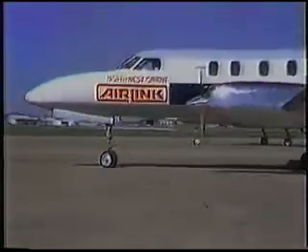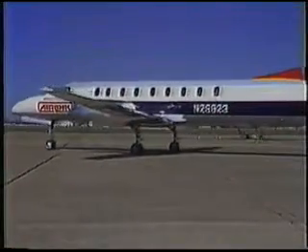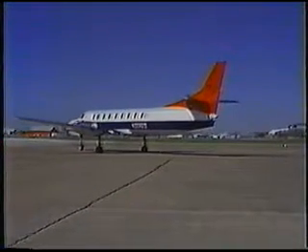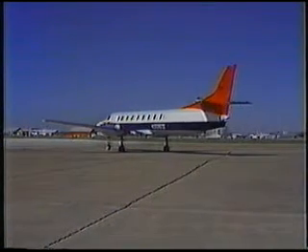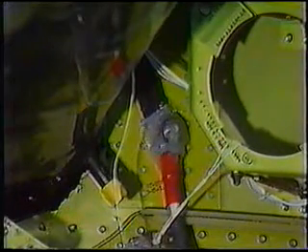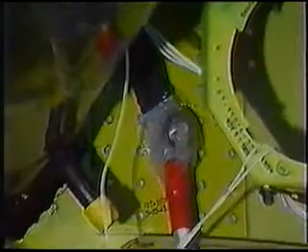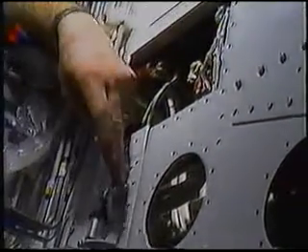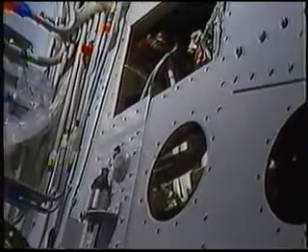Proper operation of the DC distribution system is an absolute necessity for successful operation of the electrical system on board the aircraft. Let's look at some important facets of the distribution system. An area frequently overlooked in troubleshooting efforts is the means for current to return to the source, the grounds. One of the most baffling problems a mechanic can be faced with is a loose or intermittent ground. Even if the ground feels tight, a visual inspection is still in order. Any signs of arcing or overheating are definite causes for further investigation.